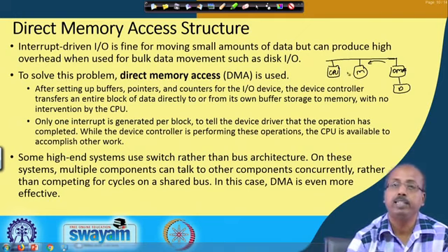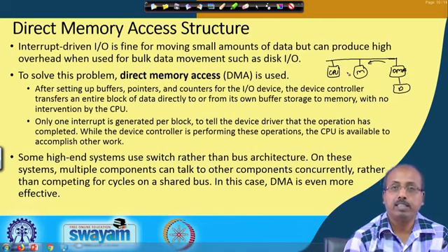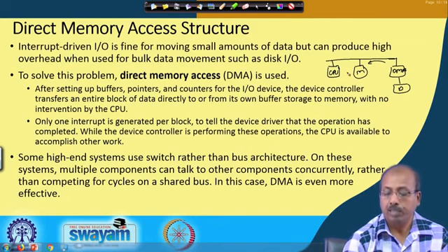So, now the CPU and DMA start competing for bus access, and that restricts the system performance. Normally, the strategy followed is that the DMA is given lower preference than the CPU, and whenever the CPU is not using the bus, only then will the DMA controller use the bus for the transfer. This is called cycle stealing.